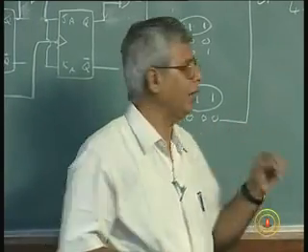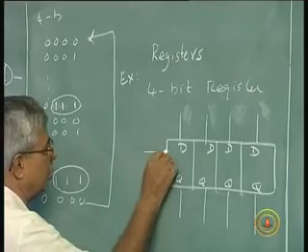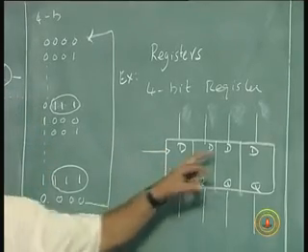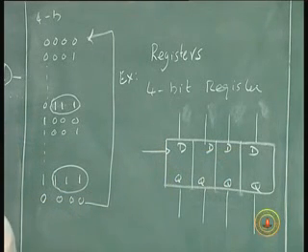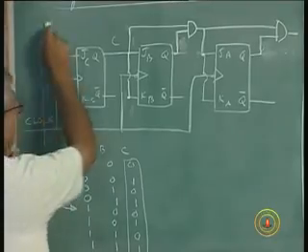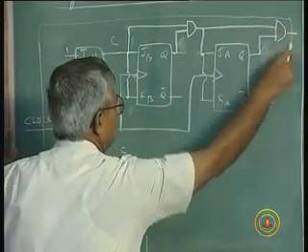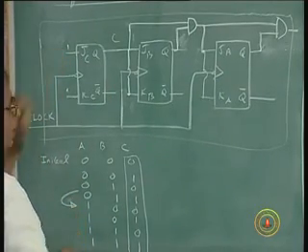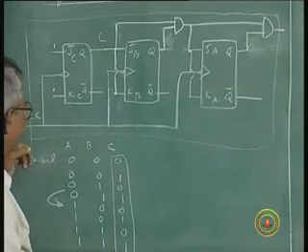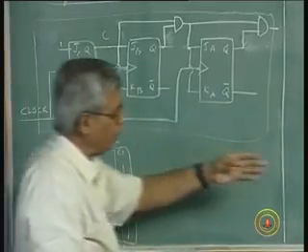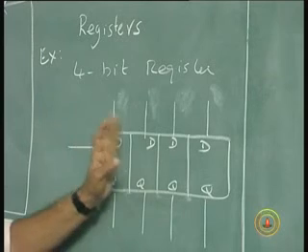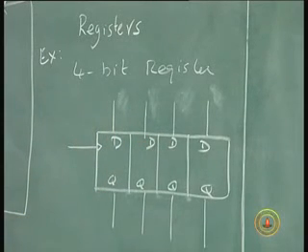Similarly, when we say one clock pulse, can be edge triggered, positive or negative, whatever, it does not mean that these flip-flops do not require clock. It's all internally connected. The clock is connected like this. Suppose I get a thing. I only see one clock, isn't it? So like that, internally they will be connected. So likewise here also I will show the clock here, but don't think that only the first flip-flop gets a clock. It is connected to all flip-flops.